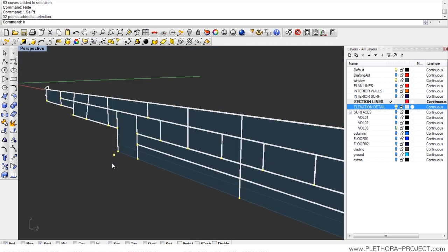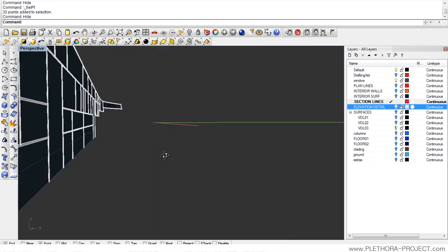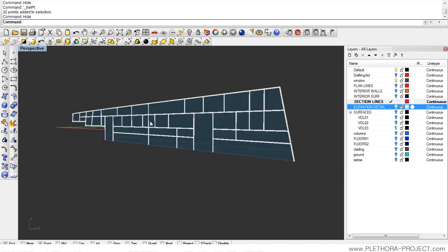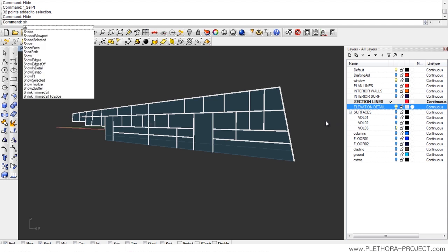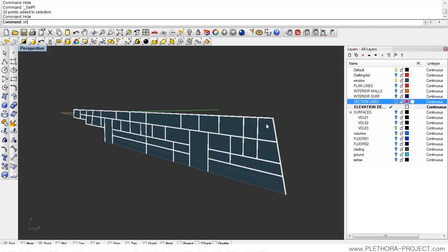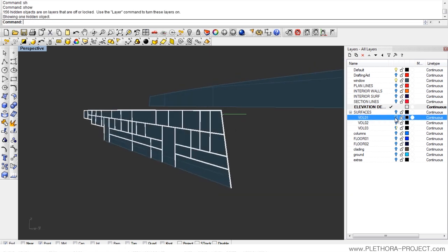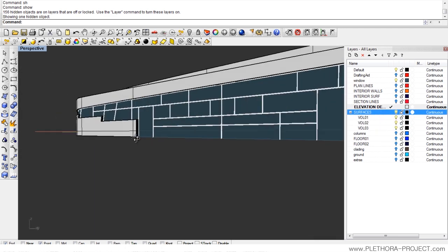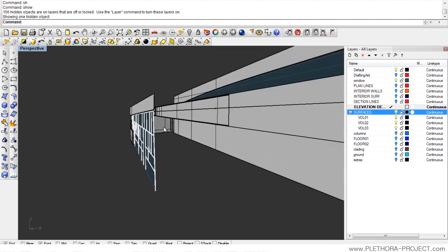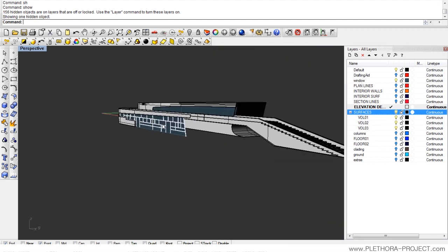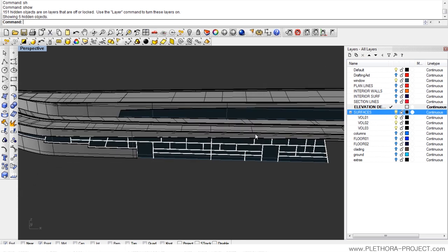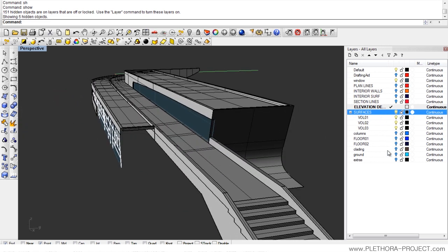We have all those points. I will hide them because they might be useful. So we still are missing like some of the details of the doors, but this is kind of pretty straightforward now. So let's switch to this layer and completely hide that one. Is there anything that we can bring back? Yes. Let's turn on what we have. So we have the details of this facade. This facade is looking pretty good. Obviously we are still missing some of the detail that it will close in this direction, but now with the tools that you know, it would be quite simple to bring that in.